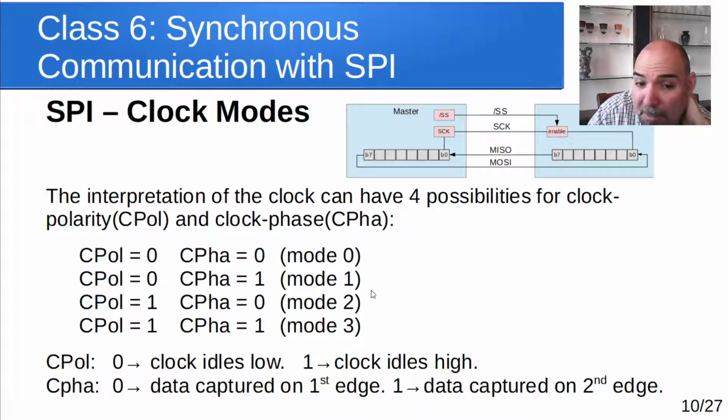And I can tell you from experience, almost every device that I've encountered supports a mode 0 or mode 3, one of those two. And really, a lot of times, mode 0 and 3 are compatible with each other, that it'll work either way. I have seen devices that are mode 1, but for the most part, mode 0 is what you see more commonly. And a lot of times, mode 3 devices will still work in mode 0. And we'll talk about why that is in just a second.